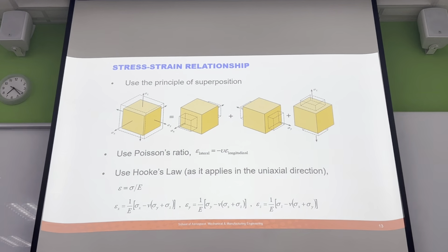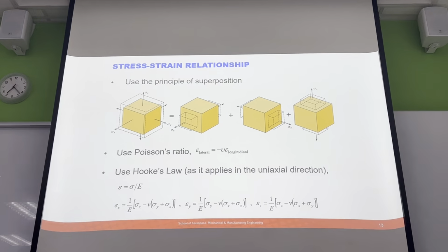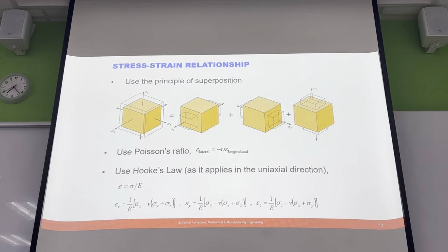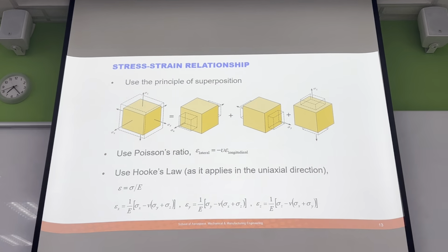So plane strain means all the strain occurs in the XY plane, but you do get some amount of stress in that Z direction. Plane stress means that all of the stress occurs in the XY plane, but you will have some amount of deformation occurring in that Z direction.